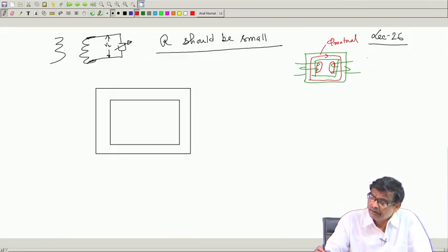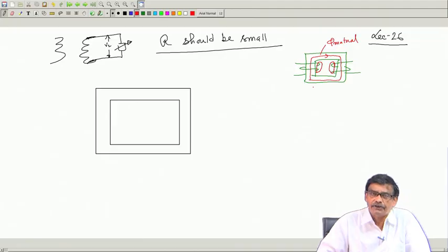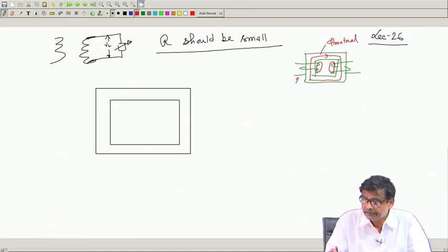So, it was represented by leakage reactance. Now, therefore, to reduce the value of regulation, it depends on R1 X1. So, R1 okay, copper you use, that is okay, but can I reduce the value of X1, the leakage flux? So, this winding is say LV, this winding is HV, whatever it is.